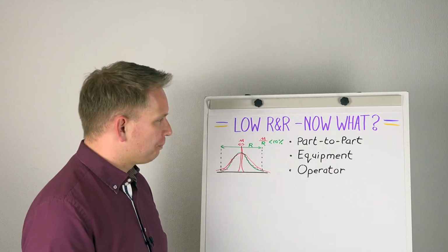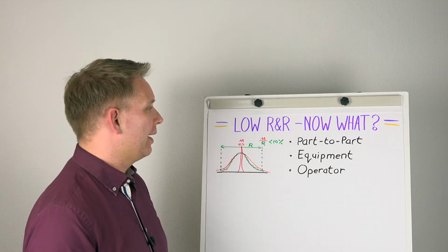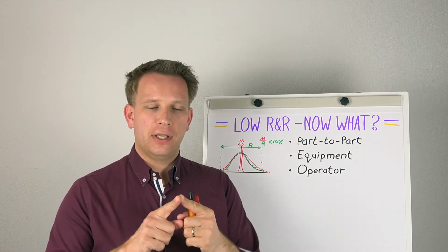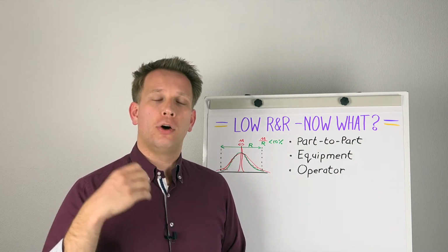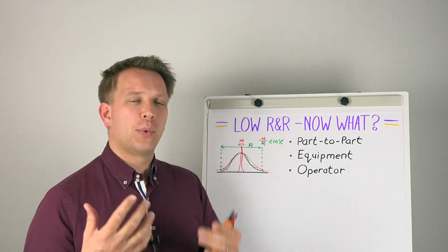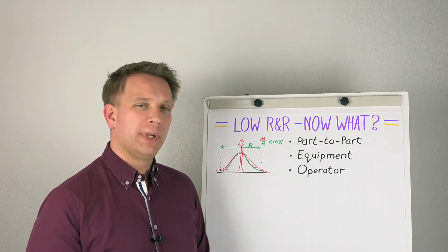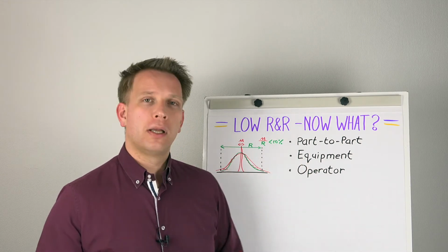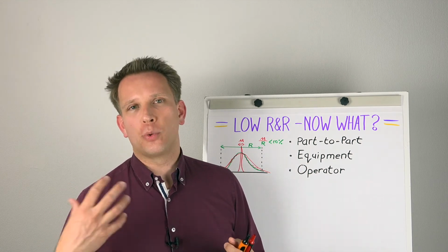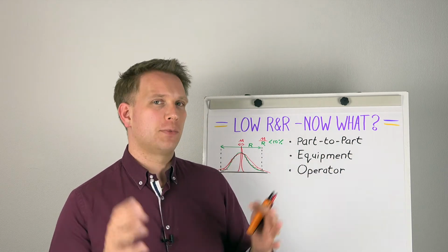The other two, the name sort of suggests it already, come in when we see that there is a lot of difference between 3 repeat measurements of the same part. Then we have a measurement that is very difficult to repeat, and probably it will be in the equipment or maybe the training with the equipment, but that's if all the operators also have that same spread.